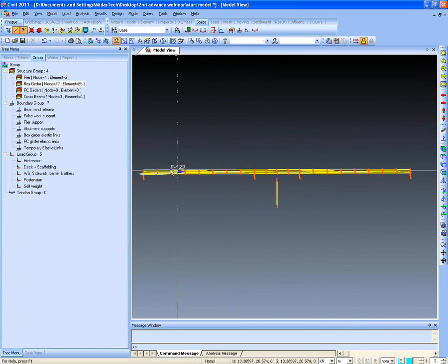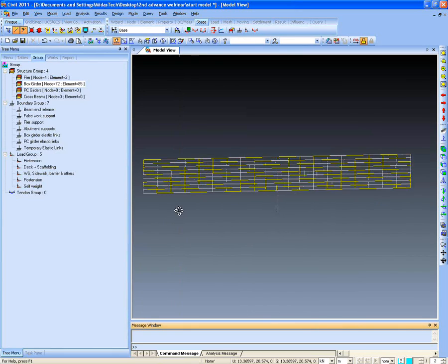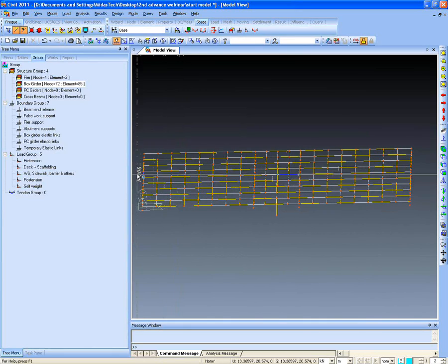Now I will select the precast girders, but here I would like to tell you that the cross beams that I have made are made to provide structural rigidity or stiffness in the transverse direction, because the deck will be continuous.